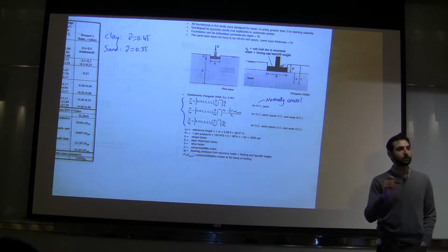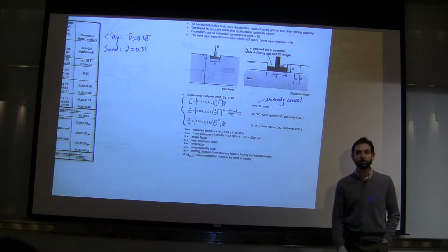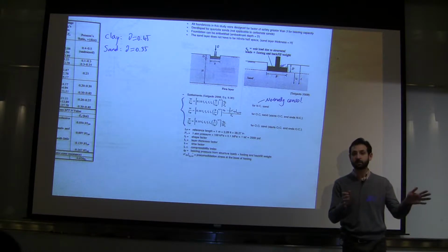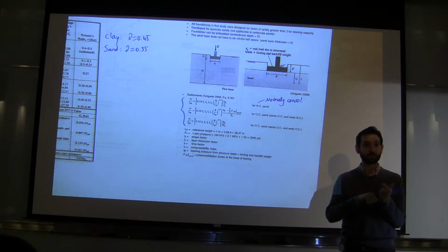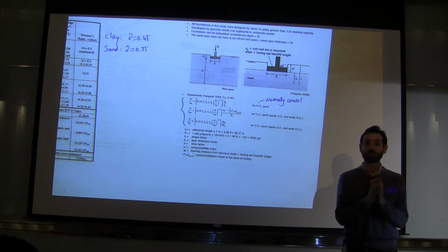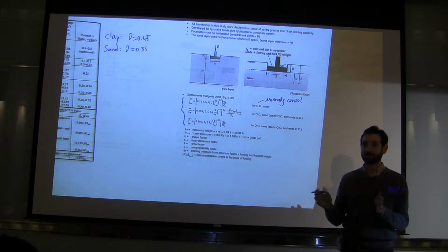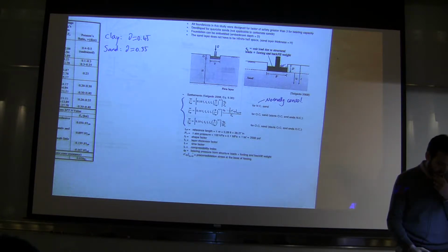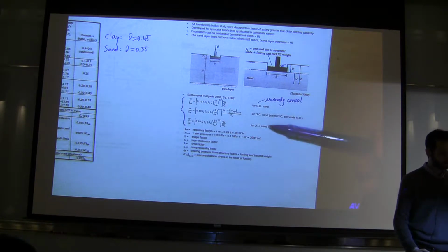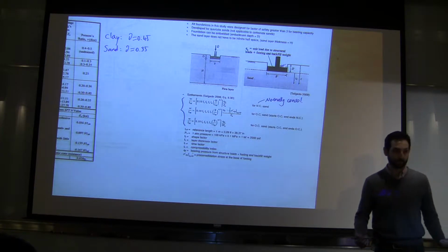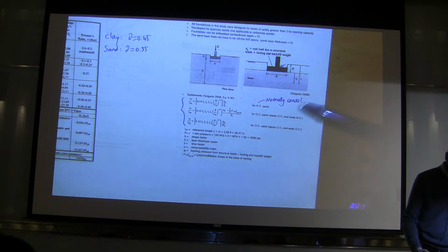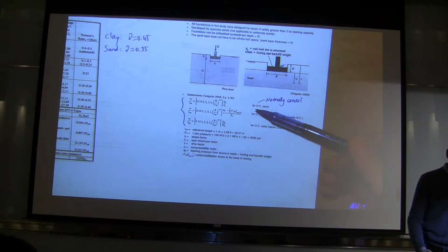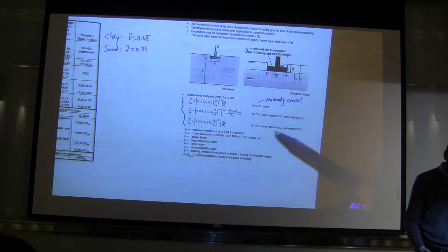So this should remind you of a lecture that we had in soil mechanics, where we were discussing the same stuff. We had case 1, case 2, case 3 for consolidation settlement. But that one was in a different soil, right? We defined consolidation in clay, not for sand. So what is this about this equation here that we are defining NC and OC for sand? And I'll talk about this in a little bit. So we have these three cases, very similar to the consolidation cases in clay.